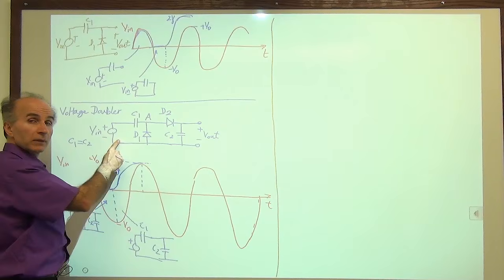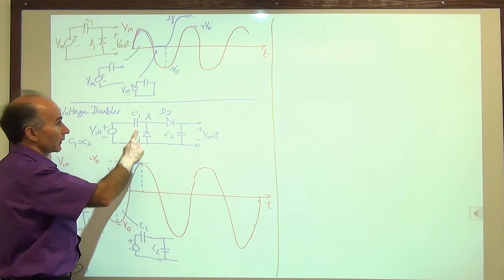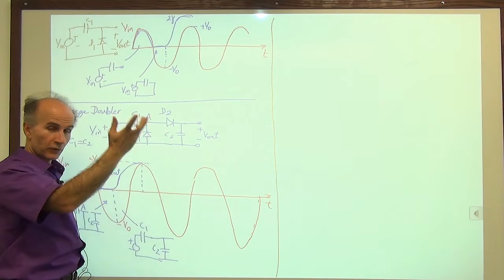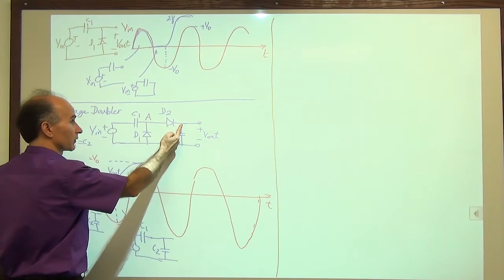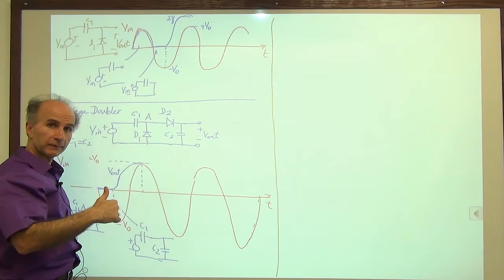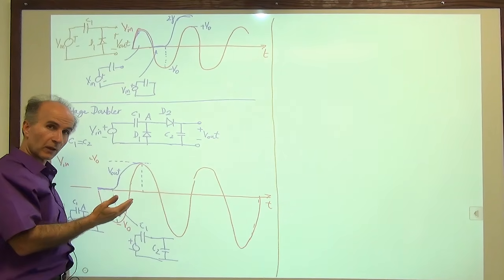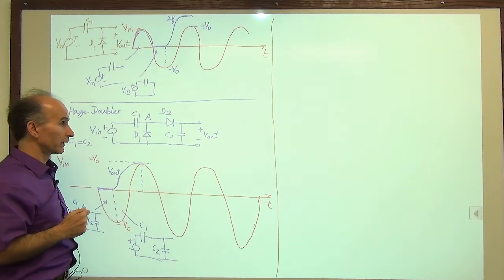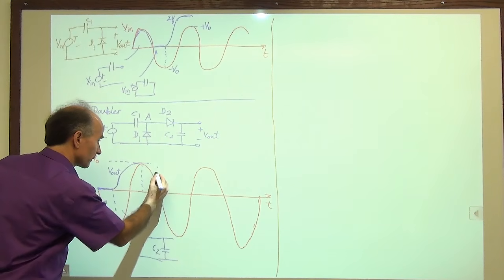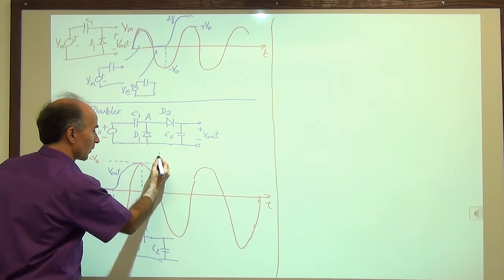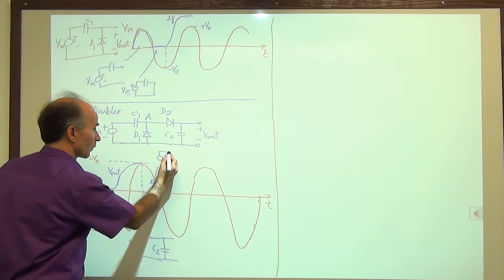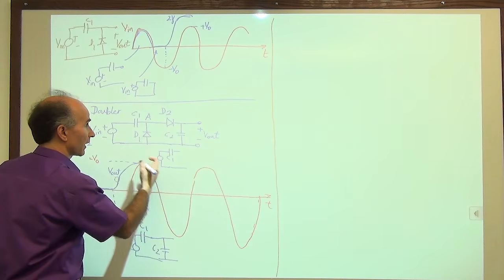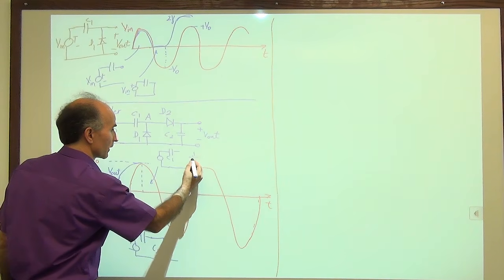How about D2? This voltage wants to go down. Now the question is, does D2 turn off or does it not turn off? Well, same question as before. Does this voltage remain constant? Does it go up? Does it go down? And if you follow that methodology, you will quickly see that D2 has to turn off. So when D2 turns off, in this regime, the circuit reduces to one voltage source, one capacitor C1, and D1 is off, D2 is off, so we have C2 only.